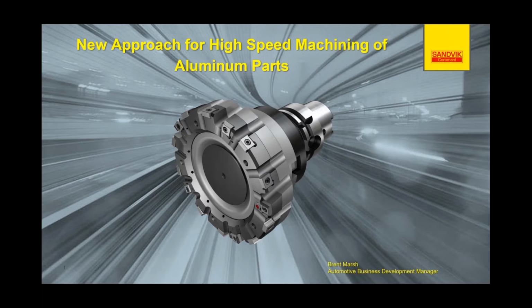You may have just a few seconds milling a surface because it's such a high rate of speed and feed, but then you've got to go back and either hand deburr it, or you've got to have a brushing tool in the spindle, something else to go over and remove these burrs.